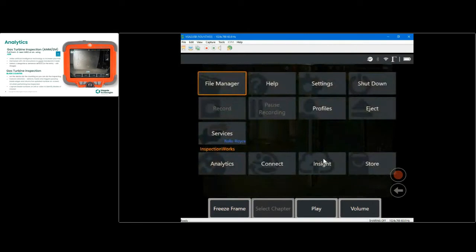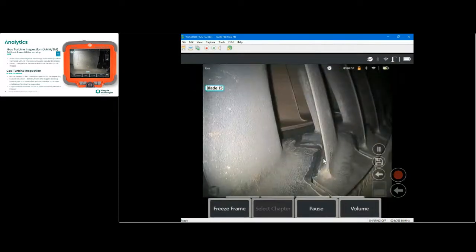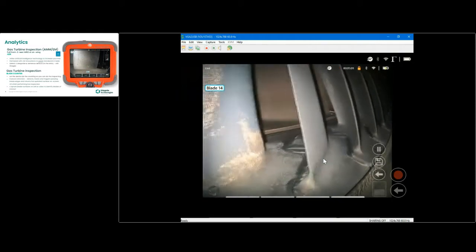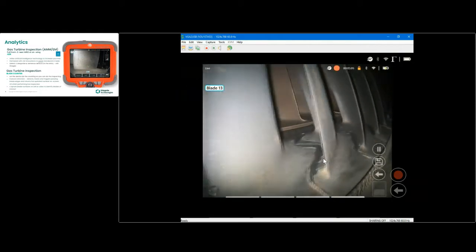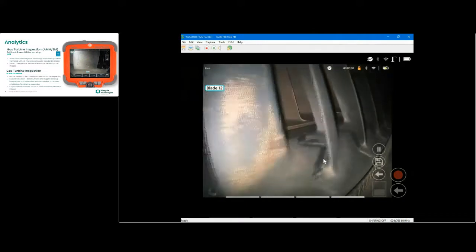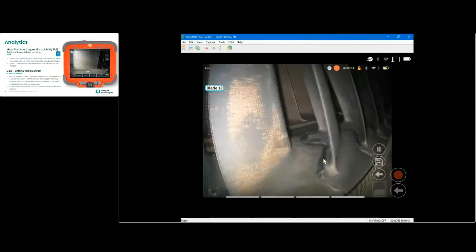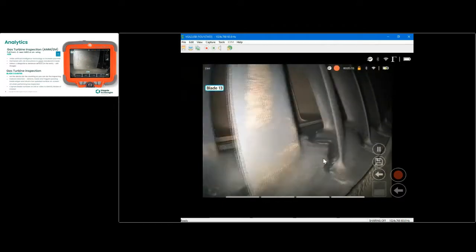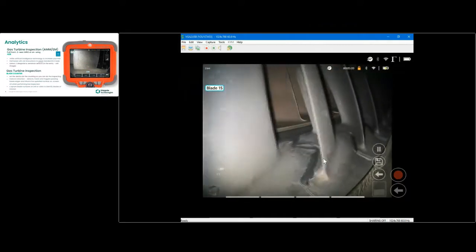Let me go back. Much smoother rotation here of the LP turbine. So there'll be a person sat in the fan inlet spinning the fan blades whilst the inspectors position the borescope at the back end of the LP turbine to inspect, in this case, the shrouds or the tips of turbine blades here.